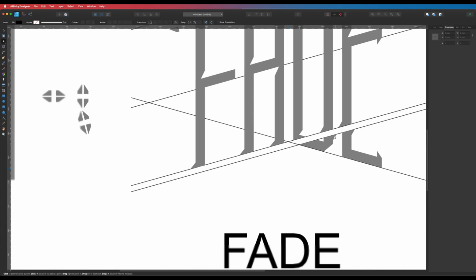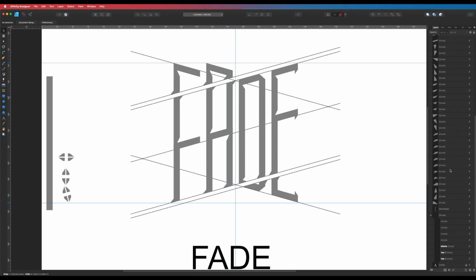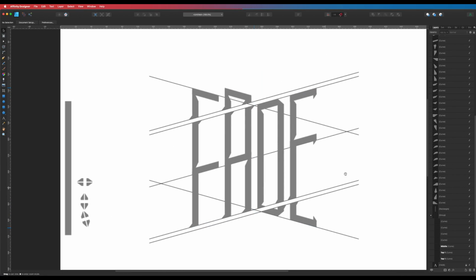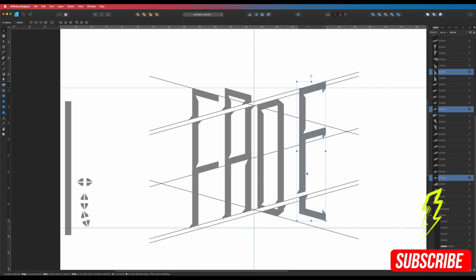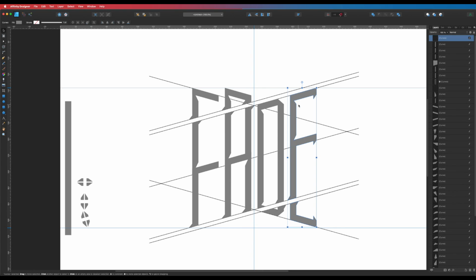That's going to be good. Okay, I think what I want to do is all these shapes over here, what we should actually do is make a copy of it, so if we have to come back we can still manipulate things and change things. But what I'm actually going to do, I'm just going to go ahead and make the bold move. I'm just going to select all the elements of my E. So I'm going to get my selection tool, which is my move tool, select all the elements of my E, make sure I've got everything, and I'm going to click add. Then I'm going to label that E.